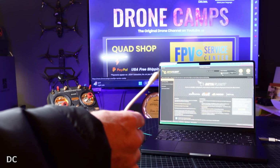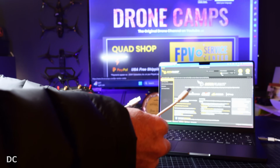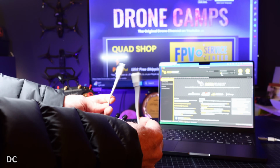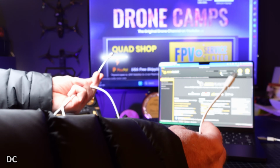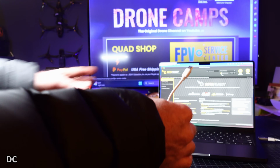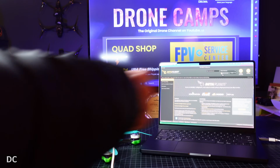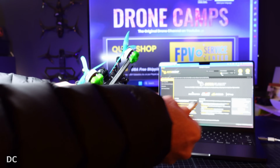There are 2 types of cables out there in USB land. There's actually a ton of different types, but even though these 2 look exactly the same, they're both white, they're both USB-C, one of these is not a data cable. You need to make sure that the cable that you're using to plug your quad into Betaflight is indeed a data cable. It shares information backwards and forwards here, and it allows you to write down to the flight controller as well as connect to Betaflight.